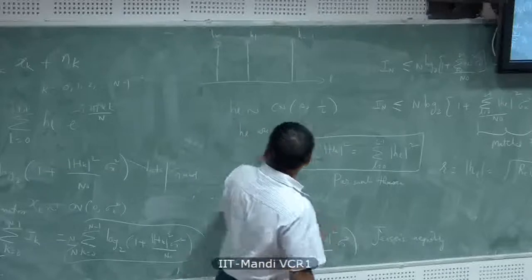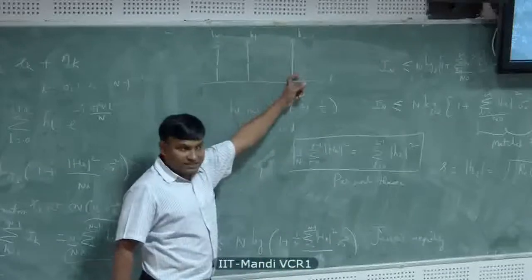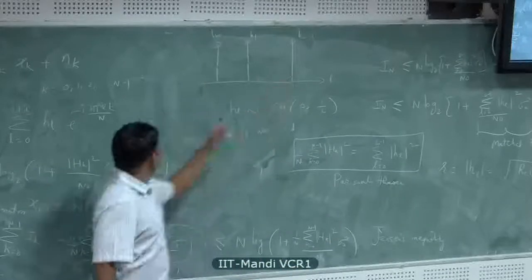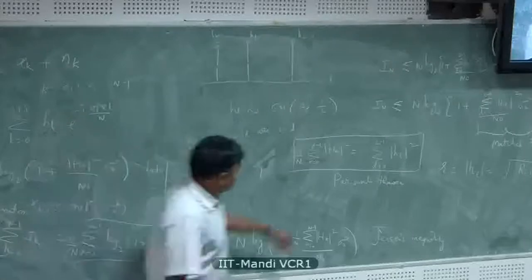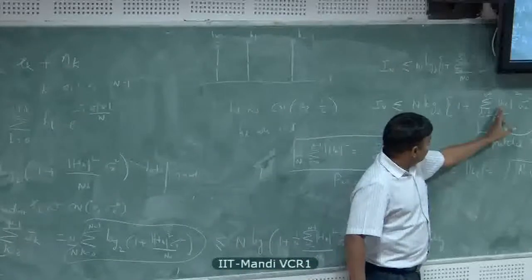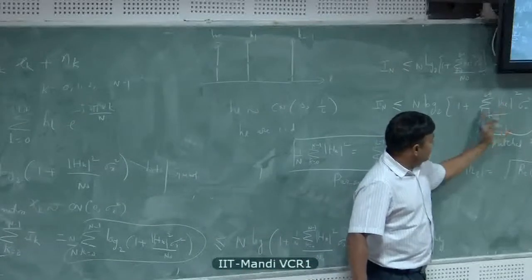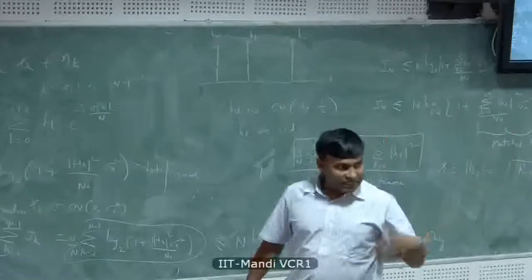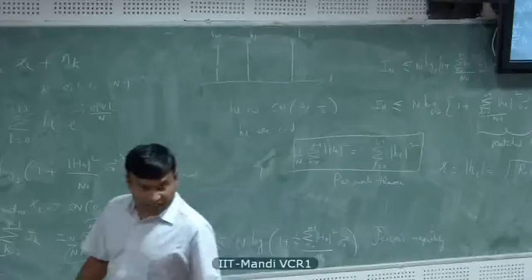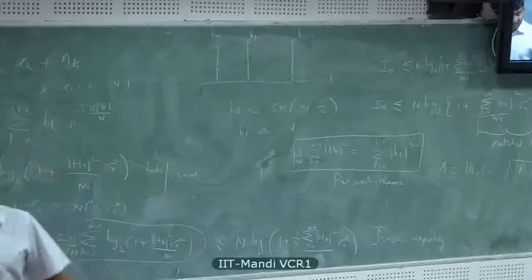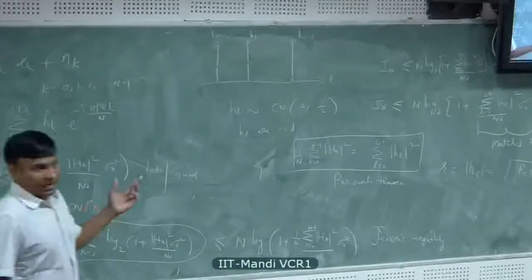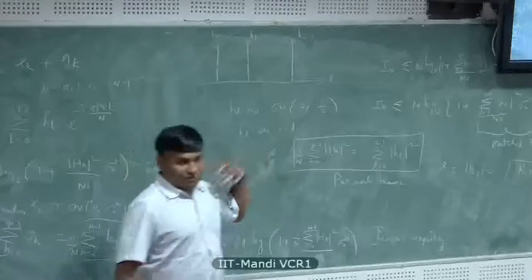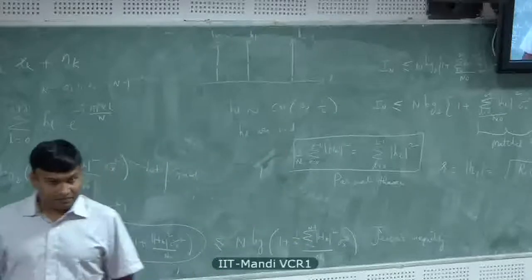But on the other hand, if you have independent copies of a given symbol xk, because we're all adding them up coherently, if one of them fades, the other need not fade. There is inherent protection given by the channel, or in this case, some kind of transmission and receiver method.